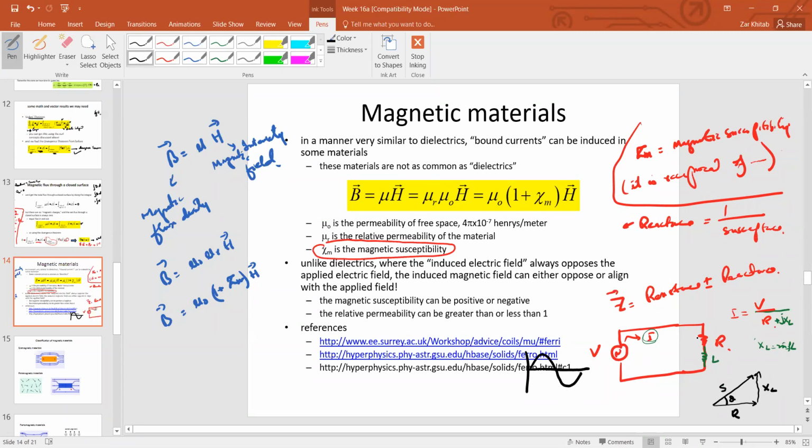So basically what happens, if you have some reactance in the circuit, it will hide some power from the real resistance. It will reduce the power for the real resistance or the real load, right? And some power will go through the imaginary part of the load during the positive half cycle. During the negative half cycle, that excessive power will be given back to the load.